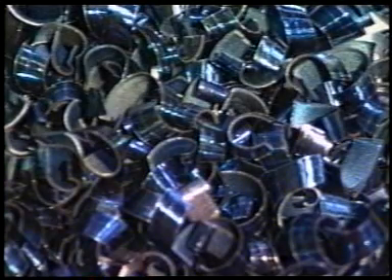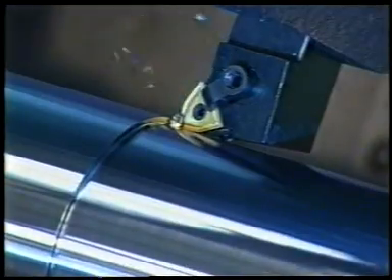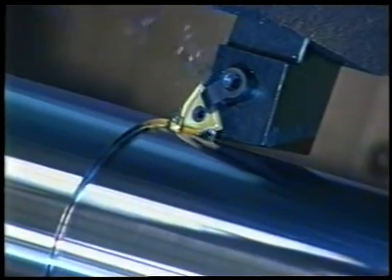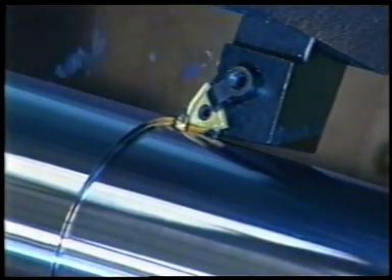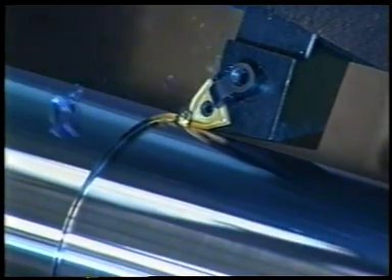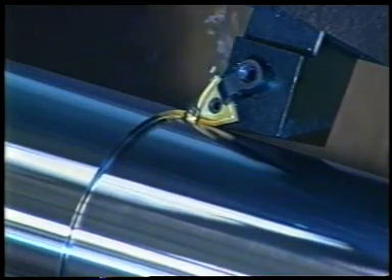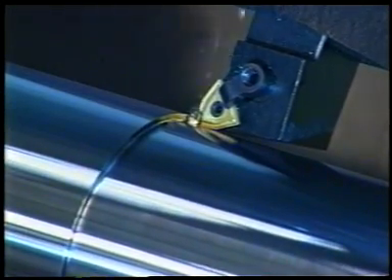In turning steel, chip color can indicate if the heat generated by the machining process is being transferred away sufficiently from the part and into the chip. A chip absorbing heat leaves a steel workpiece light gold in color, then turns blue. But if the chip immediately turns dark blue at the cutting edge, this suggests excessive heat is being generated.